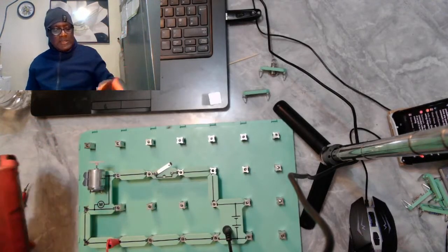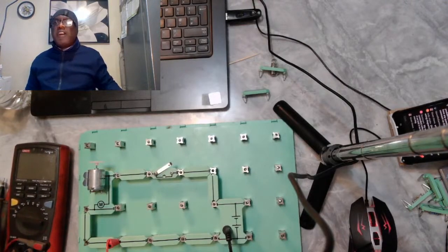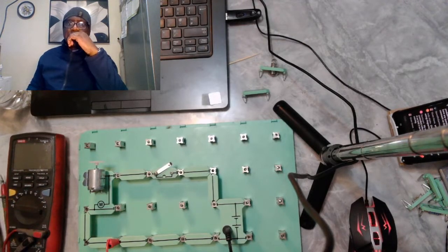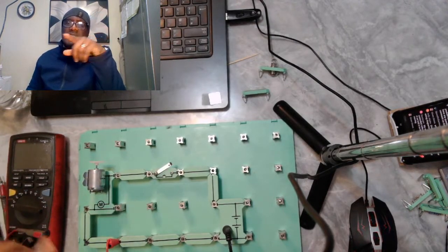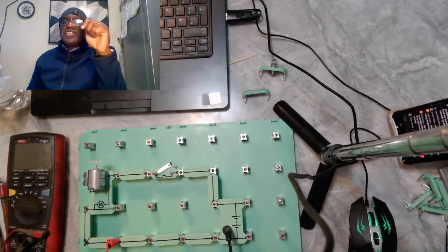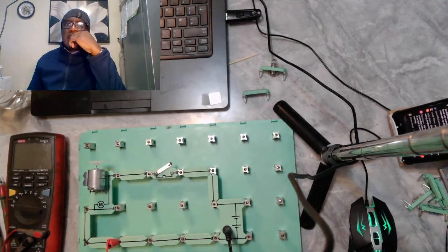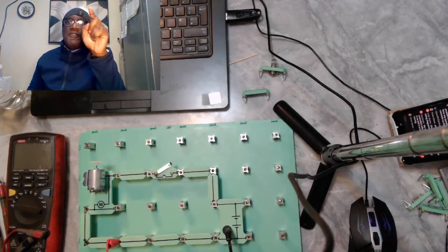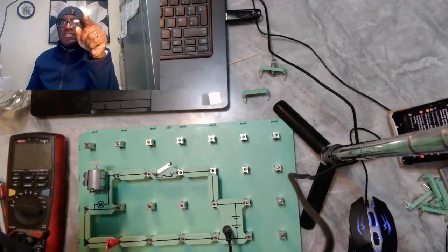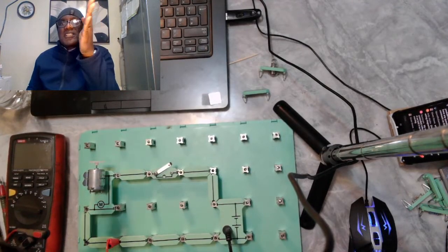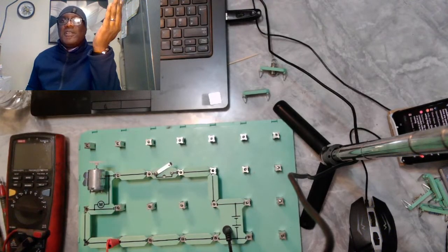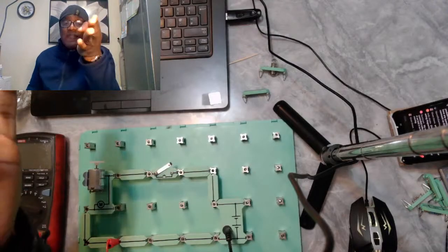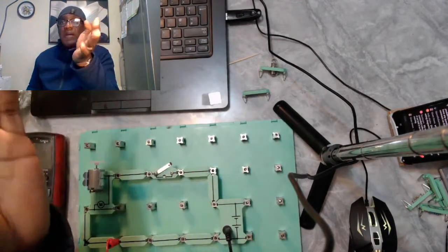And it measures 0.25, a quarter of a volt. The reason why I'm saying this is that when you're diagnosing some of these sensors, whenever the ignition key is on, they give out a signal voltage of about 0.5. So if your meter only measures from 1 volt, you are going to miss that 0.5. It will not pick it up. It will say 0 volts when there is actually a signal that is coming from a sensor.